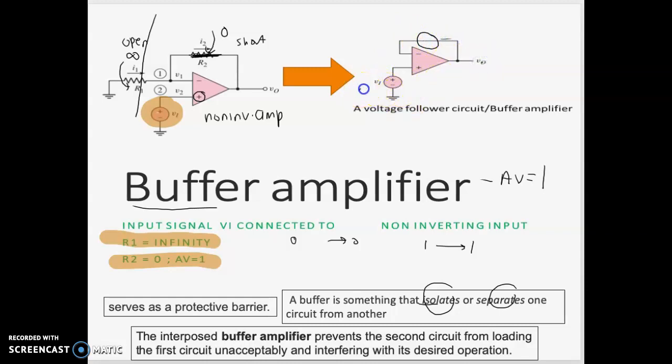So let's say I apply here 2 volt. Voltage rule number 1 says if this one is 2 volt, the node here will also be 2 volt. So this 2 volt will be brought to the feedback without any resistor, and you get your Vout as 2 volt. So what is the gain here? 2 divided by 2, that is equal to 1.